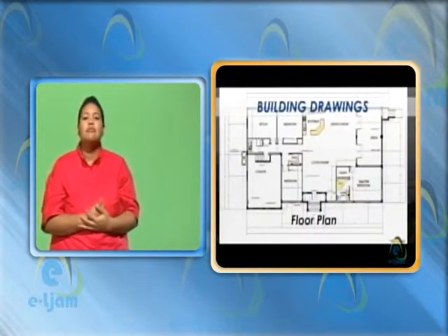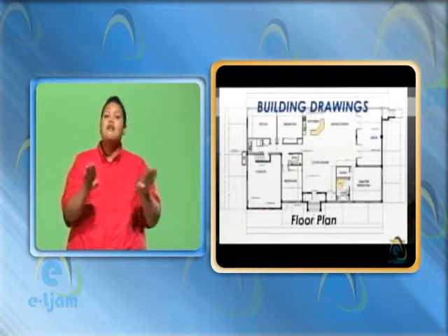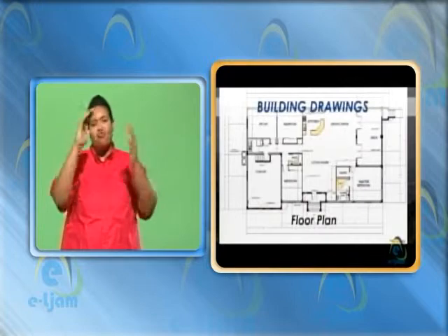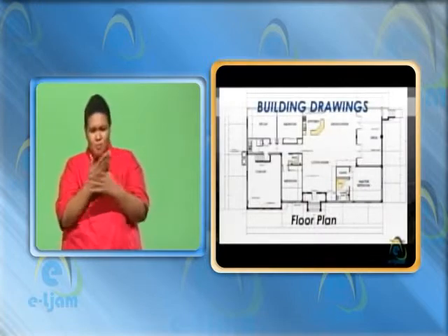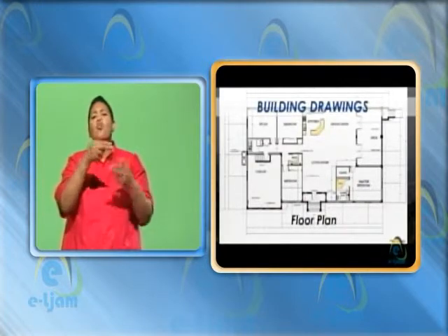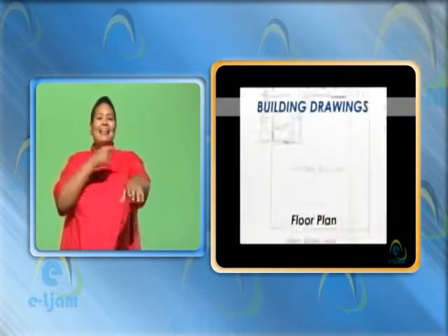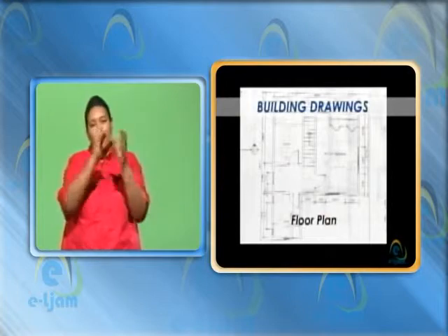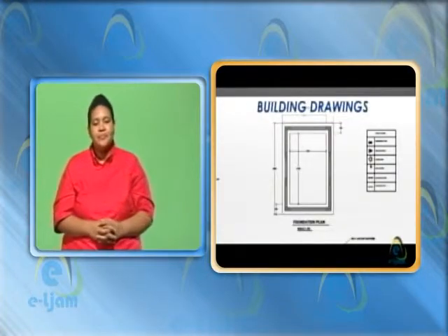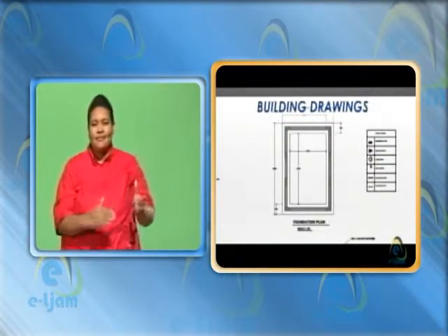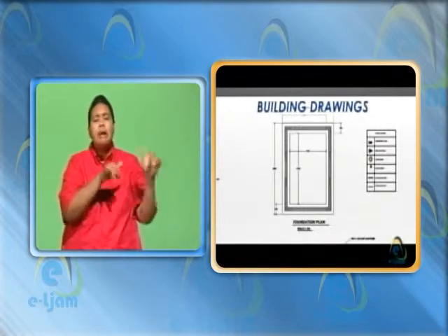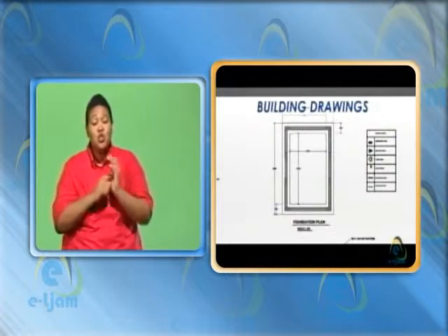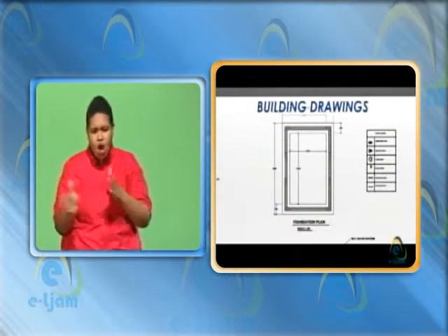The floor plan. The floor plan is an overhead view of a building with the roof removed. Dimensions are drawn between the walls to show room size and wall length and thickness. The floor plan is arguably the most important drawing. Foundation plan. Foundation plan is similar to the floor plan, but it goes deeper in the ground, and it shows how the foundation is arranged in the substructure.